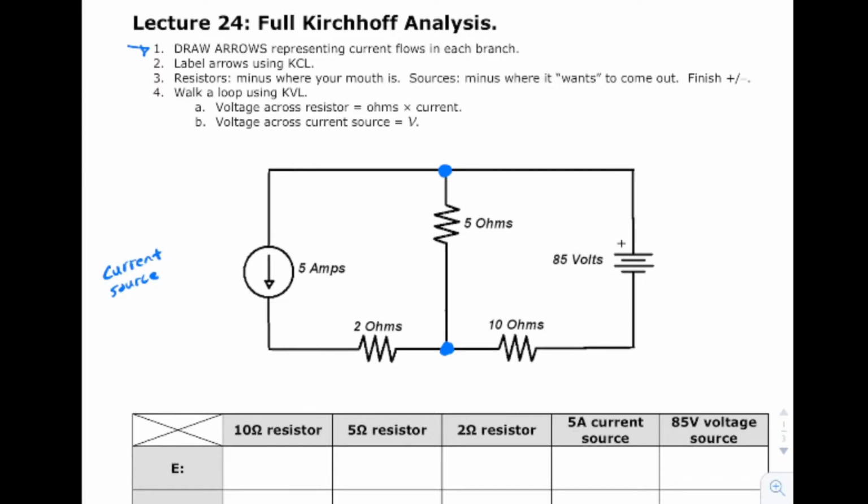I could think of 2 things, and the first is cheating. You know those power supplies that you can put on your workbench? Well, you could set it to do volts, or you could set it to do amps. So you could use one of those, but that's cheating. But the other thing is solar panels. Very common example. Solar panels tend to be current sources, not voltage sources. You get a stream of electrons, and the voltage is kind of unknown. What you know is what the current is. So I'm not saying this is a solar cell, but we know it's 5 amps.